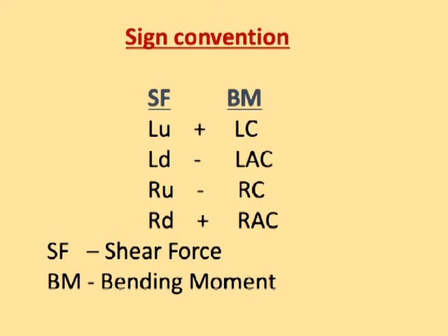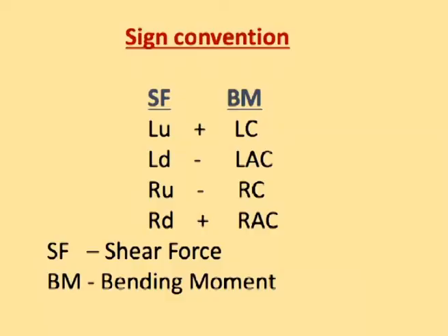So, I repeat the sign convention: left up, left down, right up, right down in case of shear force, and in case of bending moment, left clockwise, left anti-clockwise, right clockwise, right anti-clockwise, with the convention plus, minus, minus, plus.